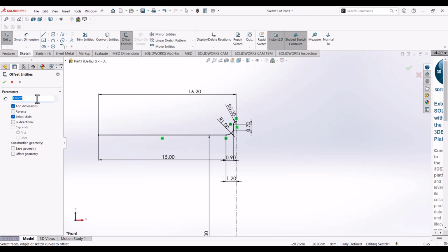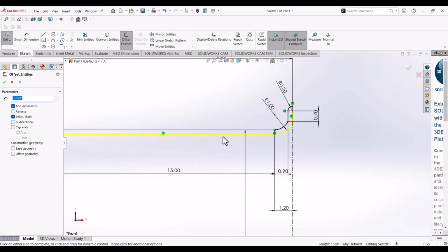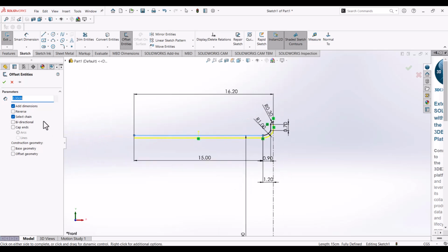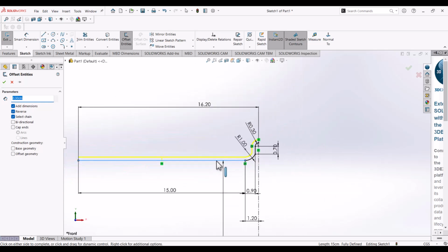The 0.5 or 0.3 here in this drawing is basically the thickness of the rim. I'm making it 0.3 centimeters. So let me select this and you will see how it looks. You see that it has given me a replicate of the line. I can choose to reverse it and it comes to the top. You see how it works. So this is the offset. If I'm okay with this offset, I can choose accept. So let me select accept here.